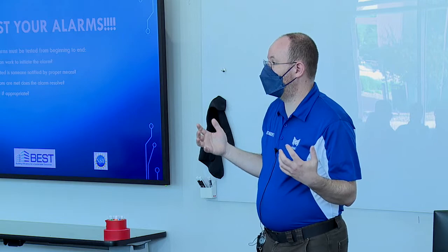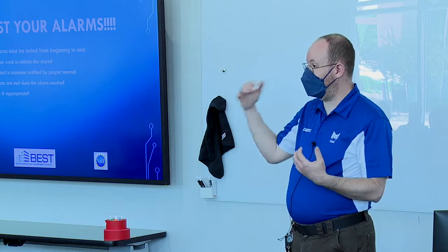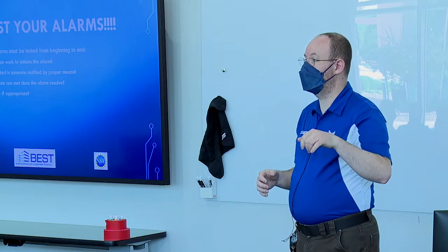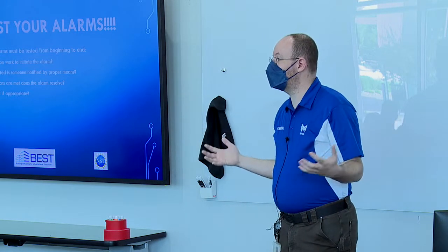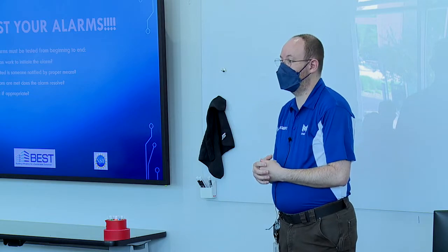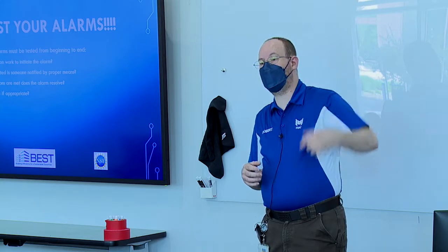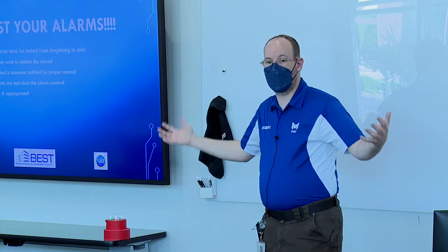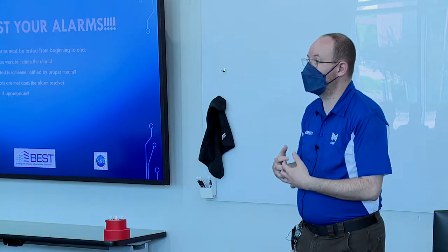Some systems are developed so that you can reference as part of the message, like we had that @ symbol for our calculation. We can use tags within most alarms to create additional information. So we can have a general out-of-range alarm that we can copy and paste down the road. And we just reference, is it the room temperature? Is it the discharge air temperature? What is the parent object of that temperature? So is it room 112 or is it room 114? Most modern systems have that ability.